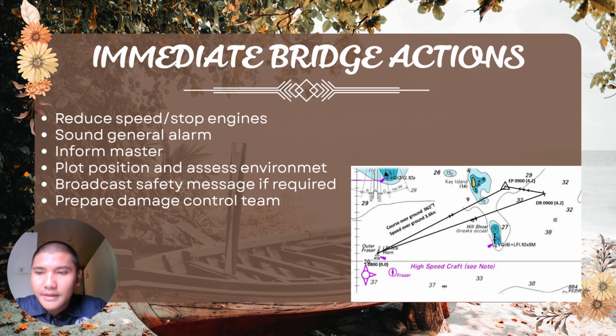Immediate breach action. The officer of the watch must immediately reduce speed or stop engines to limit water ingress. The general alarm should be sounded and the master informed. The vessel position should be plotted and nearby hazards identified. A safety message may be broadcast if necessary and damage control teams prepare.